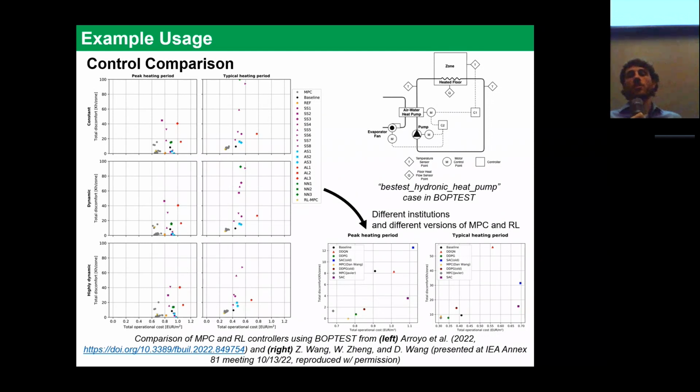And there's a distribution pump that circulates water through the floor back to the heat pump. And the basic embedded control within the model, which comes with the emulator, is a thermostat control that controls the heat pump compressor speed to heat up and cool down the water that flows through the floor.